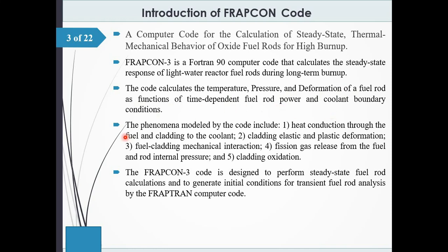The phenomena modeled by the code include heat conduction through the fuel and cladding to coolant, cladding elastic and plastic deformation, fuel cladding mechanical interaction, fission gas release from the fuel and rod internal pressure, and finally cladding oxidation.